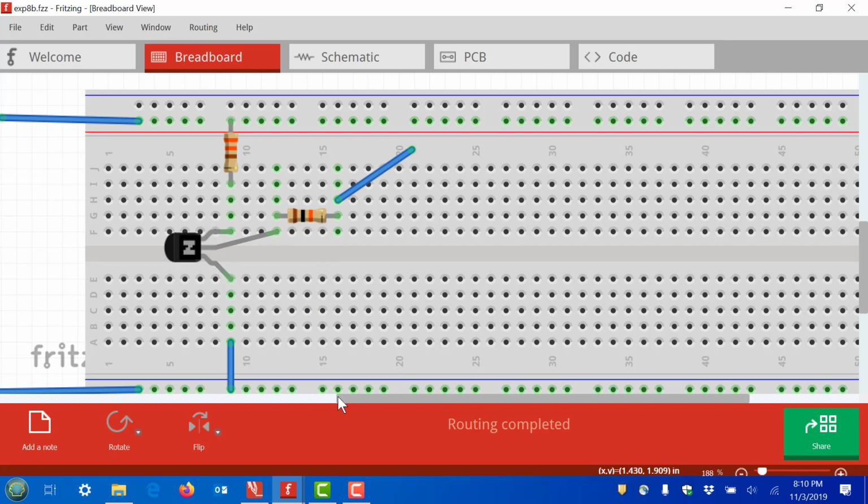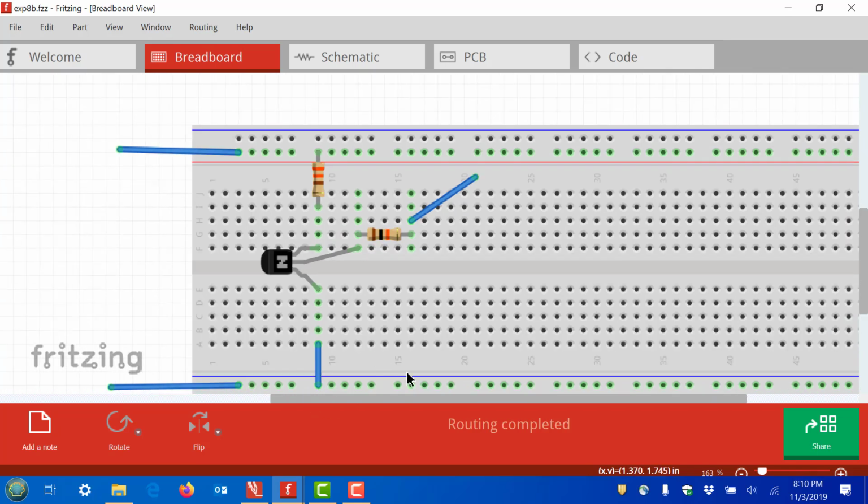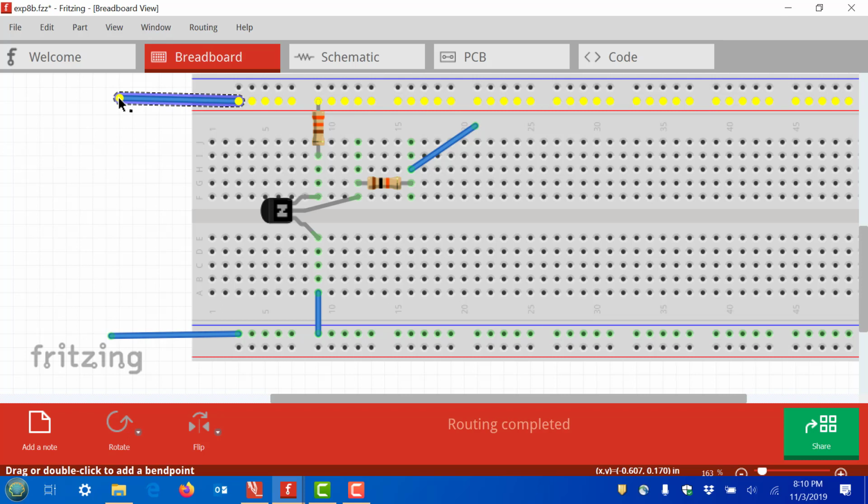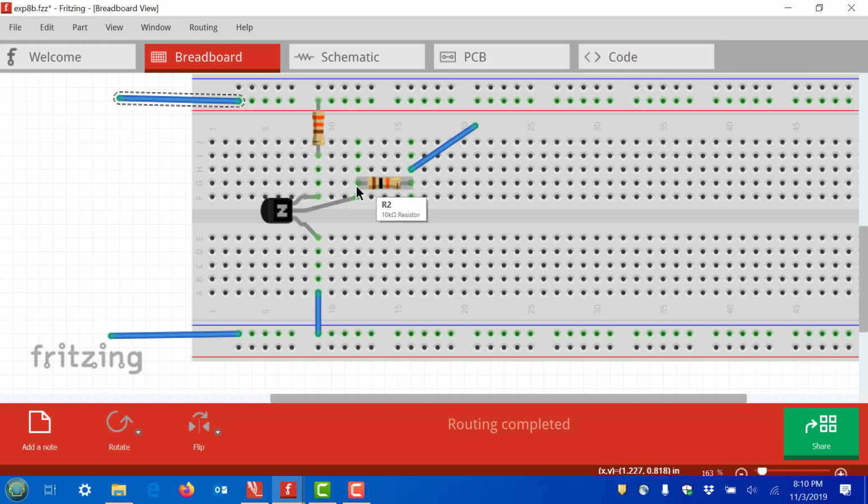And now what I've done here is obviously I have taken the 5 volt here, and 5 volt is at the top line or top level, the rail, and then we have 330 ohm to the collector, and I have this 10K. Again, these two are connected right here, and then I have 10K, and I have this lead, and so what you put here at the top of this lead is the VIN, basically, right?